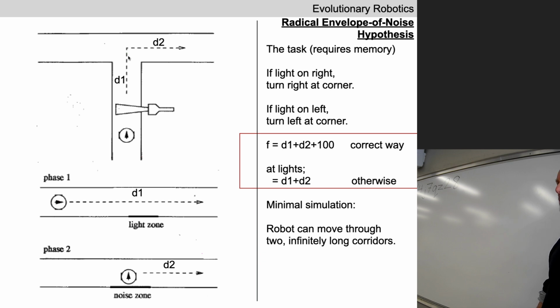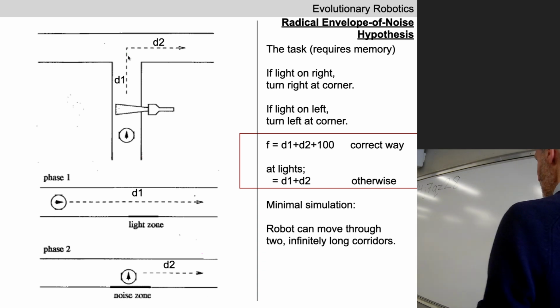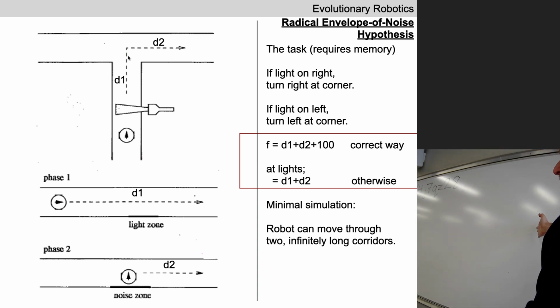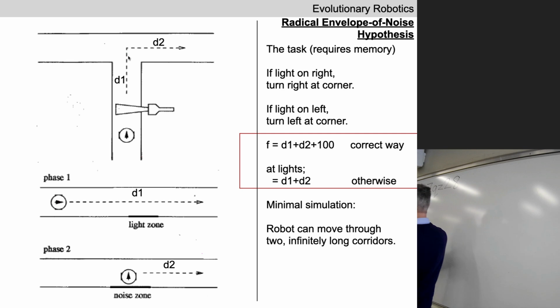Anyone ever played with actual infrared sensors before? We were just talking about how finicky they are. They're pretty good if you have an infrared sensor and you're more or less facing a relatively flat surface with a uniform reflectivity. So if I had an infrared sensor here, it would work pretty well here. If I start to face more and more obliquely to this surface, the infrared sensor is going to get a little bit noisier.